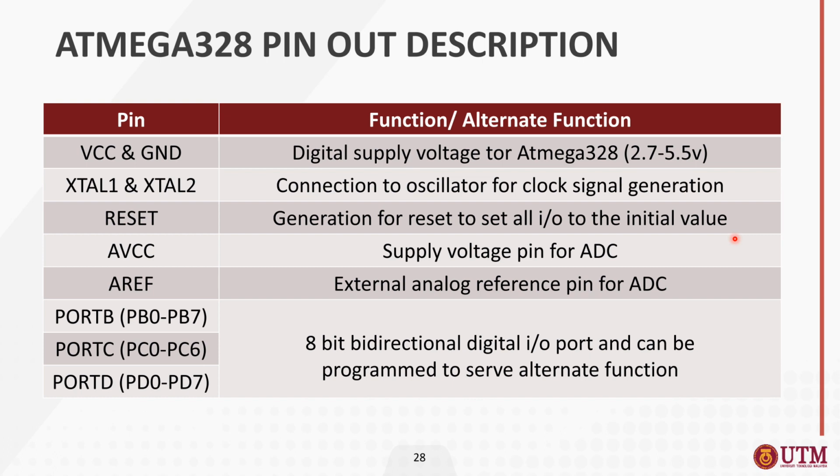So next is the AVCC. AVCC is the supply voltage pin for ADC, and AREF is the external analog reference pin for ADC. As I have mentioned, if you want the reference voltage for your analog input or analog output to become higher or lower than the current reference, which is 5 volts, you can connect your pin to AREF.